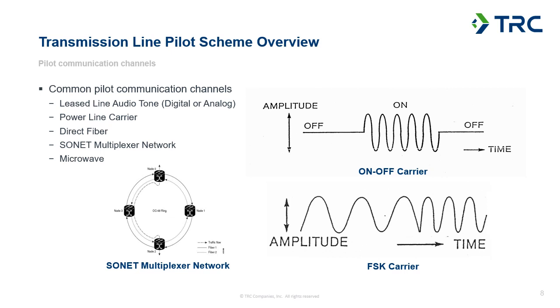More commonly these days, we're seeing a lot more utilities move towards installing fiber optics on new transmission line installations. So I think I mentioned in the first class and showed a picture of an optical ground wire. When you're putting up new transmission lines or you're refitting old transmission lines, it's pretty common practice to include fiber optics in that design, one of those OPGW ground wire configurations.